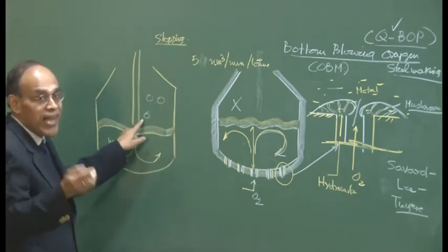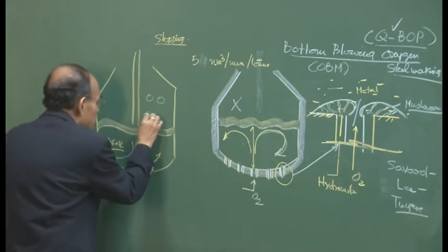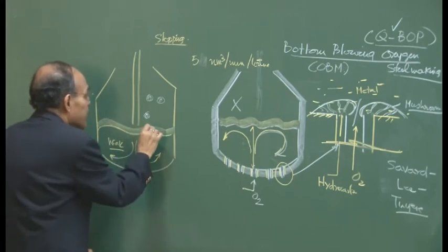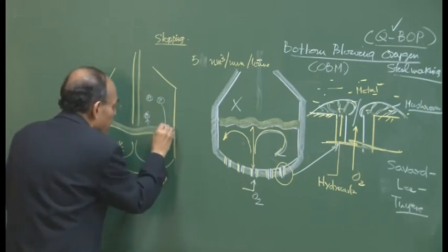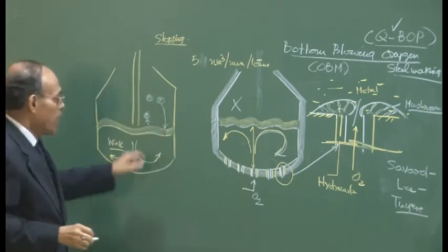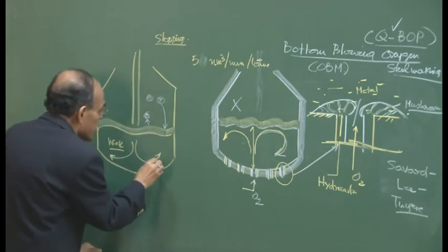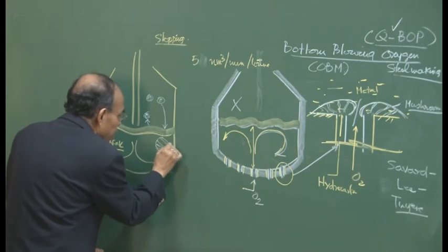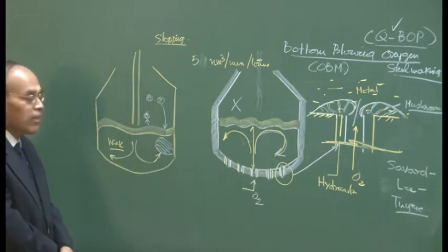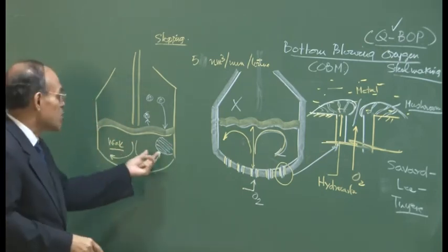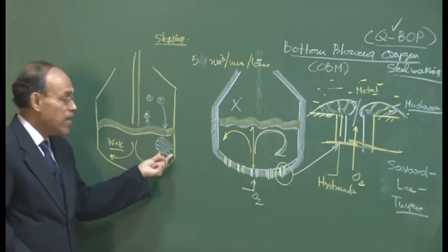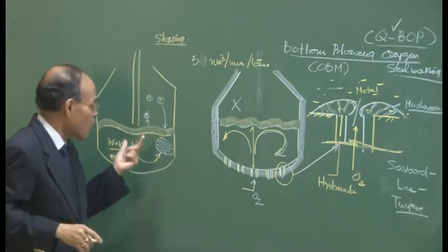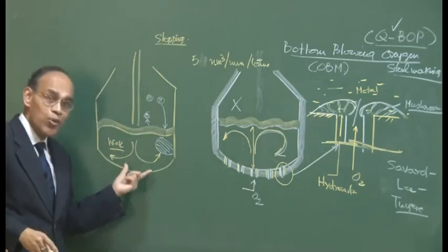As the carbon monoxide bubble escapes, the droplets of metal become heavier and then come back. And the bath is not well stirred. There are regions where the hot metal accumulates, and it has a lot of carbon in it. Okay? It is an inhomogeneous bath.